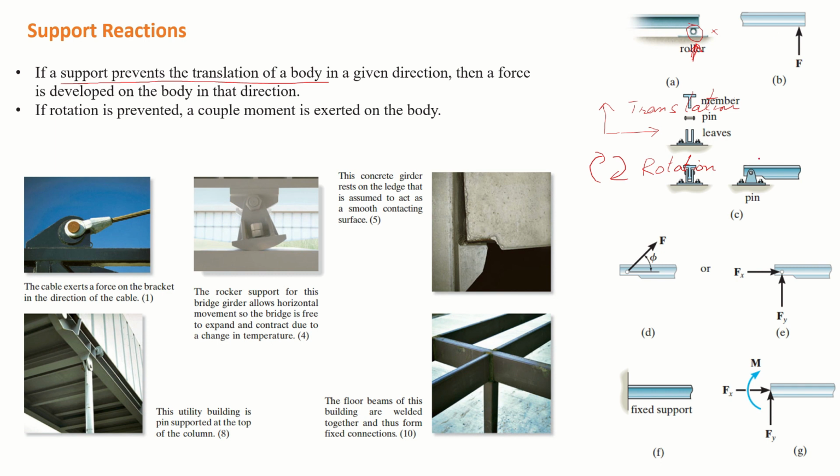Then we'll examine a pin connection. This is a pin point, and we can see that this beam cannot move in x or it cannot move in y. So we will now place two forces in x and y, but this beam can move in rotation.